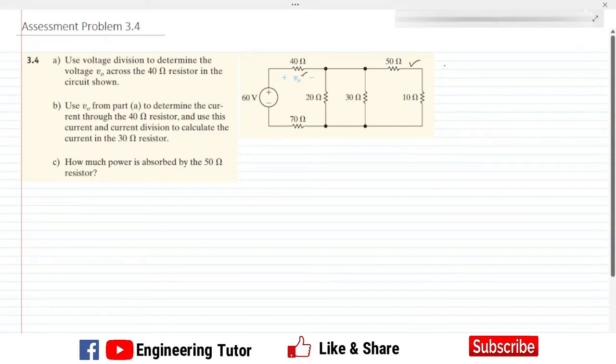In order to find the value of V0, we will apply KVL here. Let me start from here. Applying KVL, according to the KVL, the source voltage is equal to the voltage dissipated across the 40 ohm, which is V naught, the voltage across the 20 ohm, and again the voltage across the 70 ohm.